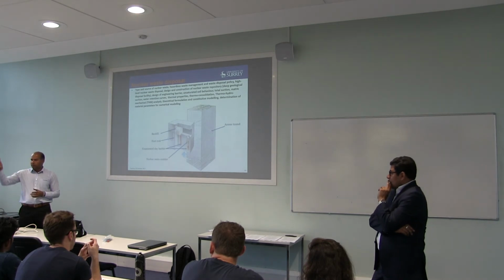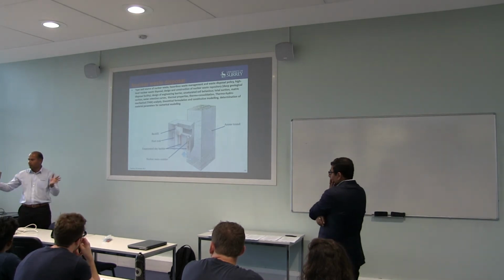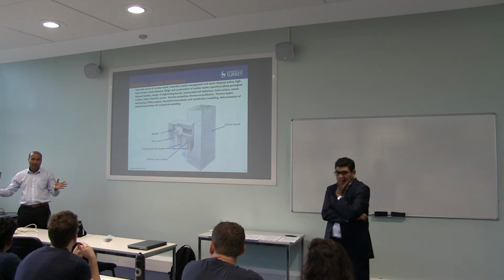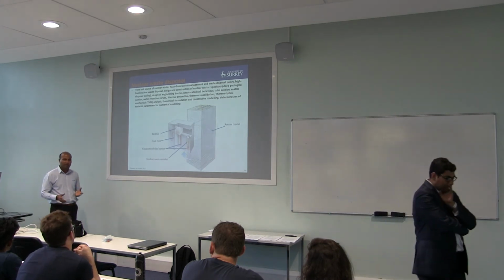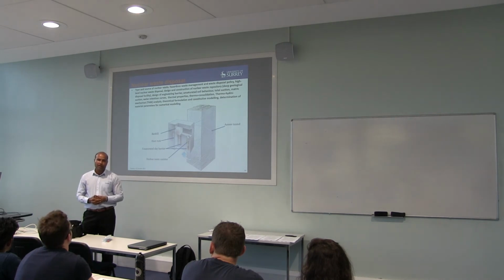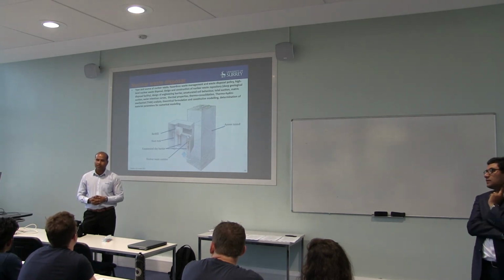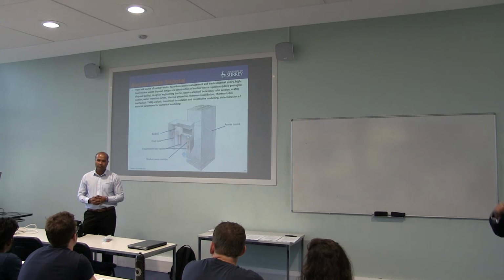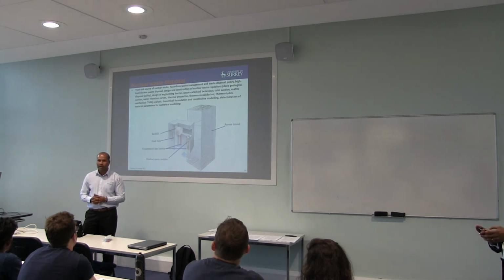With sand, when you put water, it drains out very easily. But with clay, it's not so. You put the water, and water will take ages to come out. And that creates a consolidation problem. If you know, the Leaning Tower of Pisa was leaning because it was on very soft clay. That clay was compressing slowly as the water was coming out.